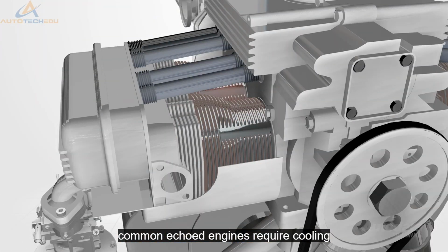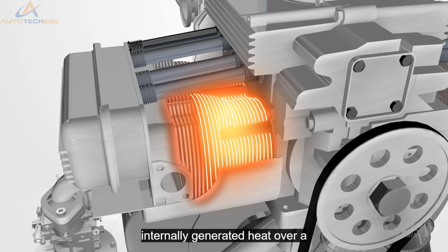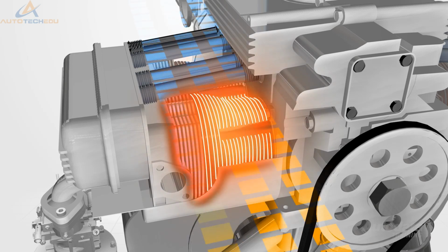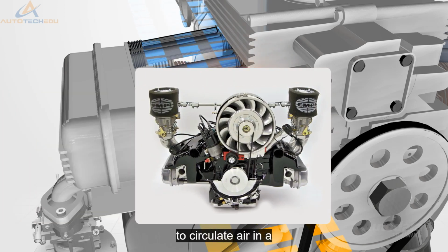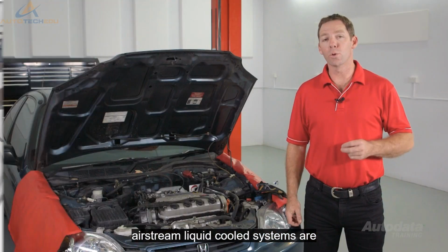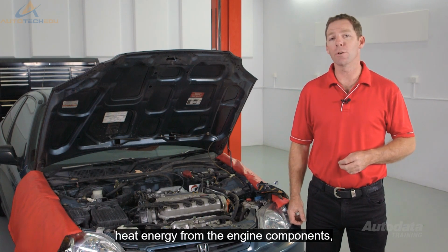Air-cooled engines require cooling fins on the outer cylinder. These distribute the internally generated heat over a much wider area. Airflow over these fins removes the heat energy. Some OEMs may use a ducted fan to circulate air. In a rear-engine vehicle, this is very important, as the engine is enclosed and does not sit in the main airstream. Liquid-cooled systems are much more efficient at removing heat energy from the engine components.